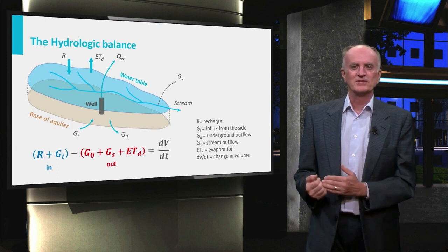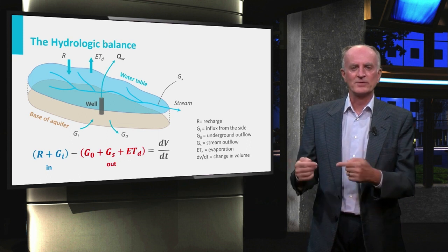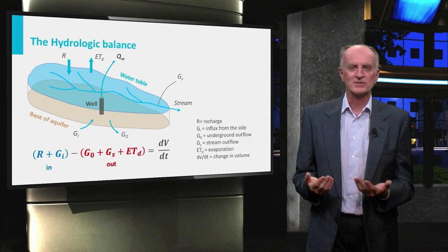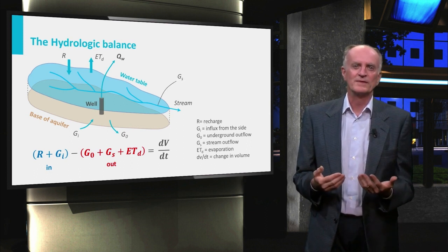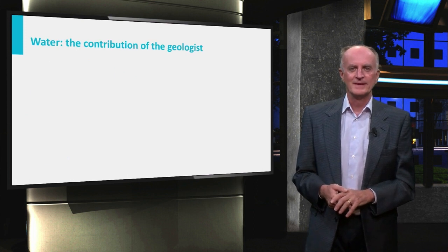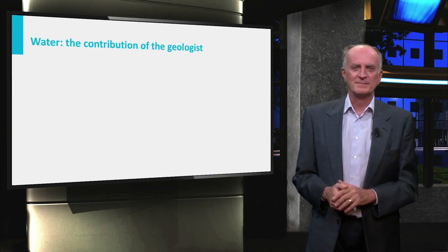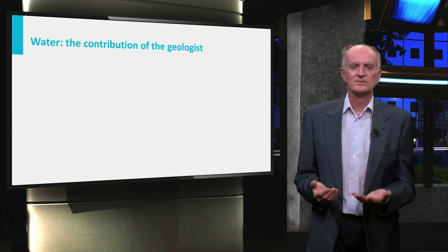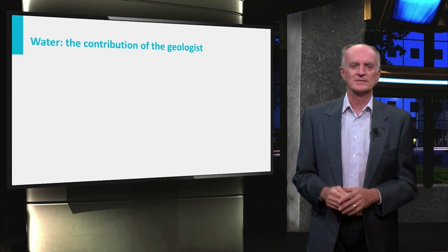If this is not sufficient, there will be a decrease in water volume and of the water table. Clearly, a non-sustainable situation, unfortunately one which occurs more often than one would like, is being generated. From the small flow exercise above, it is clear that the correct definition of the geometry and the physical properties of the aquifer is key to successful management of water resources.